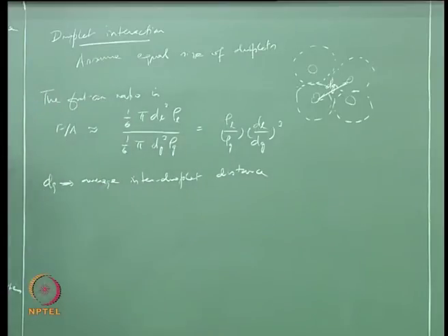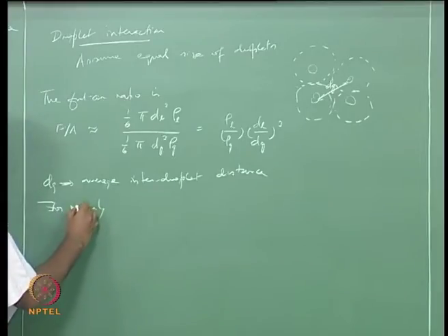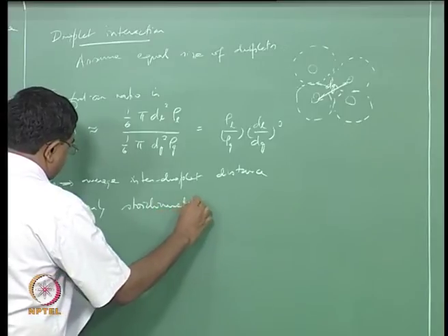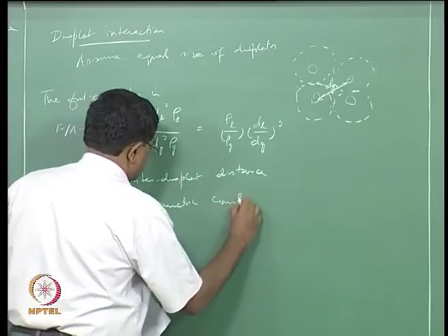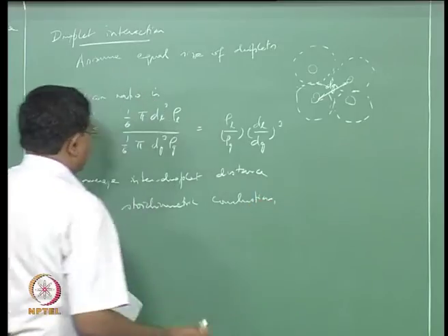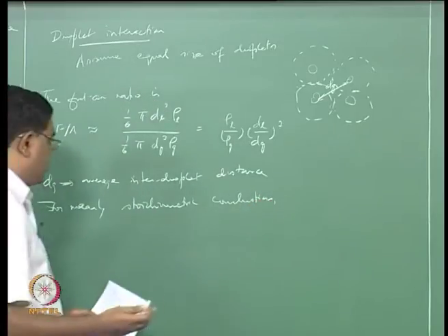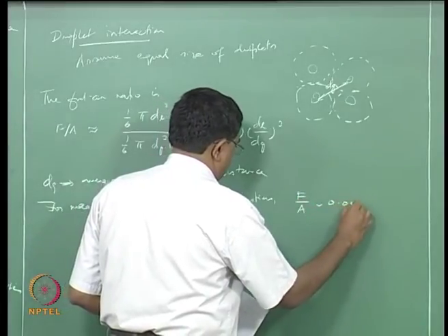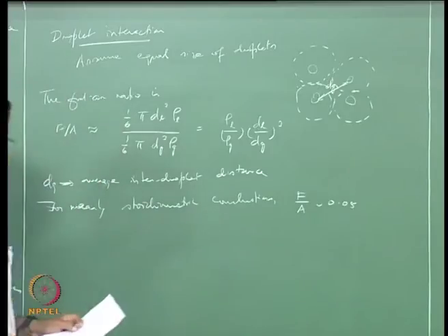So what this means is, of course, for nearly stoichiometric mixture, stoichiometric combustion, for typical liquid hydrocarbons, your F over A should be around 0.05. You can evaluate that for typical cases: you look at the stoichiometric chemical reaction, which is balanced, and then you can look at the mass ratios for that.